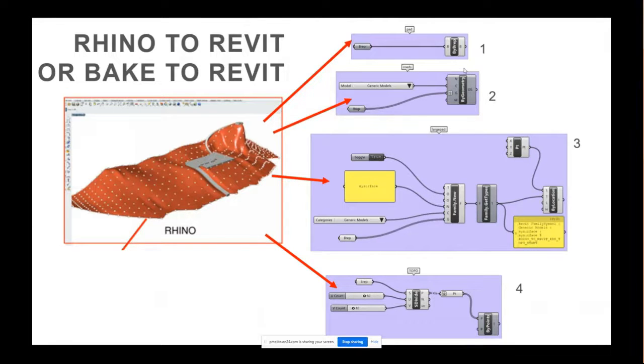It's very limiting, because at its extent, you're able to do option 2, which is basically you're allowed to bring in geometry into Revit. Well, that's what this prep node is here, geometry. You're able to assign a category. You're able to assign a material, and you're able to assign a name. Now, that is sometimes desirable because it is one step above just bringing in all the geometry in one category. The advantage here is that it can bring geometry in a bit more meaningful way.